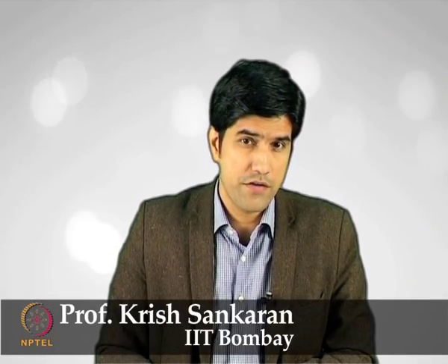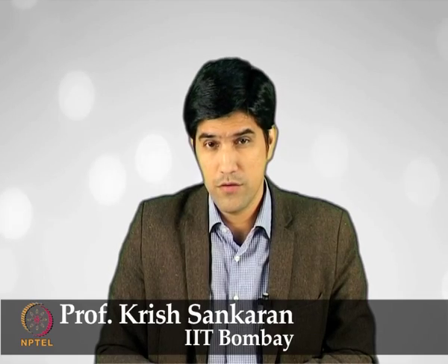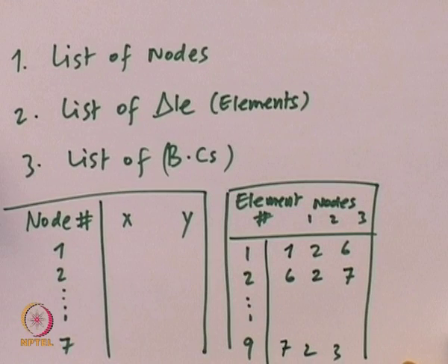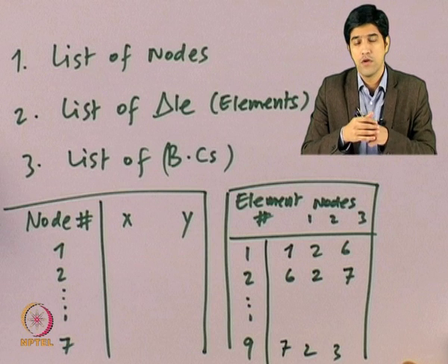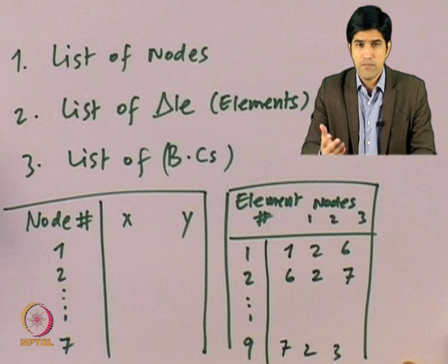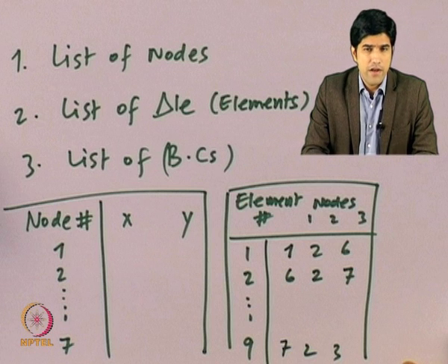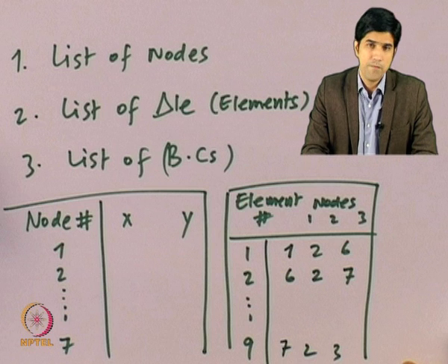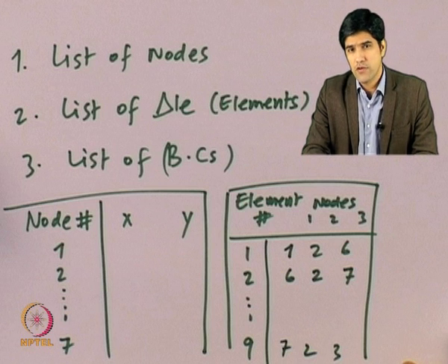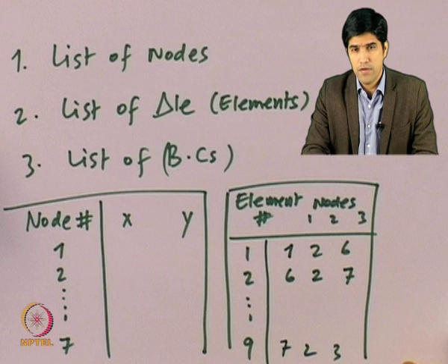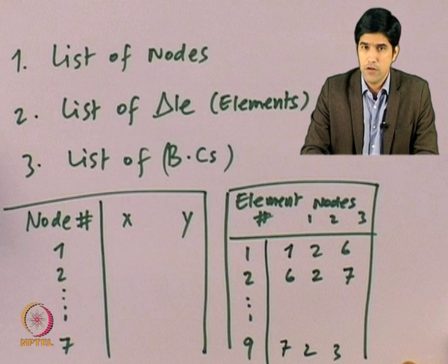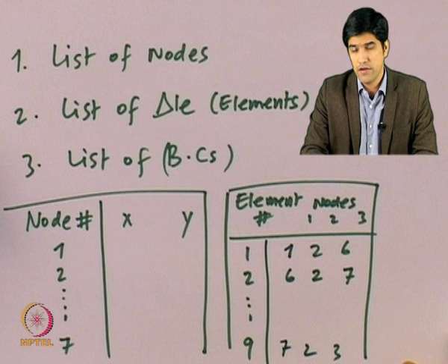Finite element method gives us the flexibility of using unstructured grid, but it is also a pain to work with unstructured grid because we have to do intensive bookkeeping in terms of managing the number of nodes, number of elements, what they are connected to and how they are connected to, so on and so forth. So when I am working on finite element method, without telling you how this entire gamut of manipulating and using the unstructured grid in the numerical methods that we are going to use is a very important step, and I don't want to leave without saying a word or two about how we are managing the unstructured grid itself.